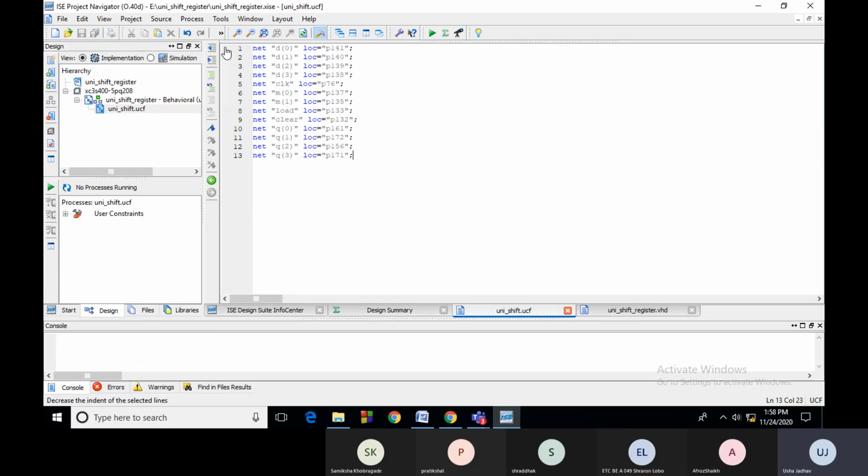So I will save it. So always instead of equal to, we are using concurrent assignment as less than and equal to, right? So everywhere I will just do it as less than and equal to, which is a concurrent assignment of your pins, right?